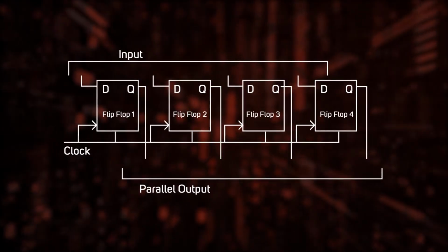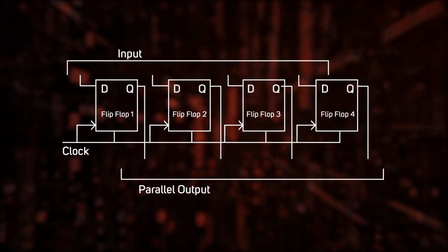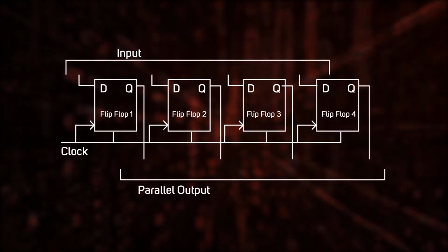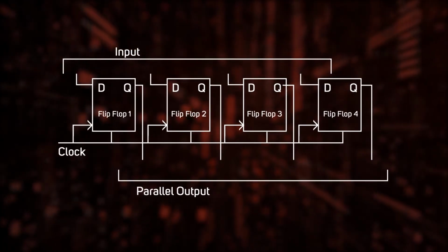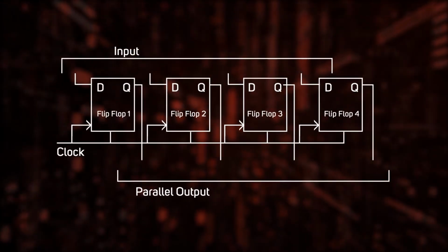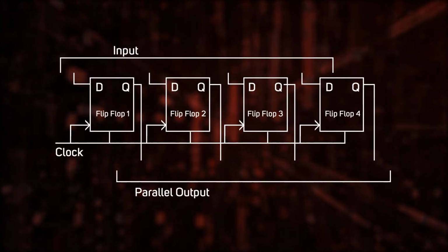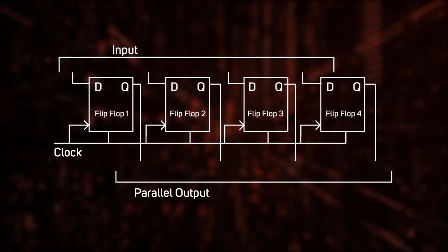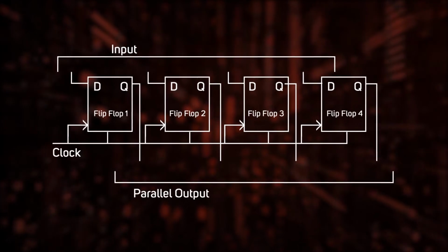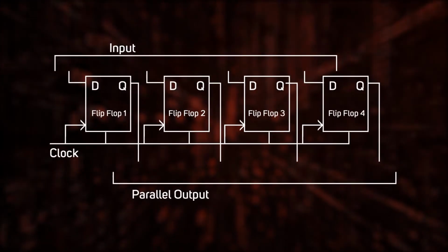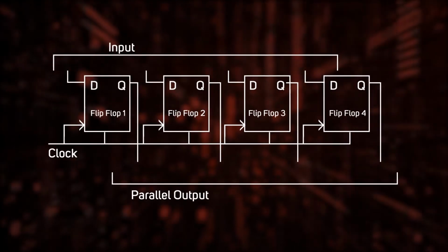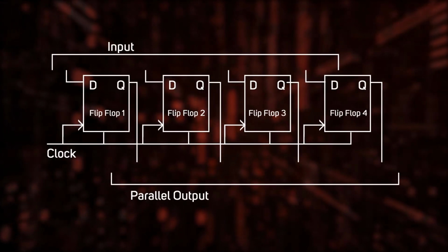When you compare it with SIPO and SISO, the method of entry of data values into the register was different. There, the data was loaded in a serial manner. Here, the data enters in a parallel mode. And at the rising edge of the first clock pulse itself, all the 4 bits will be loaded into the flip-flops and will be available at the outputs.